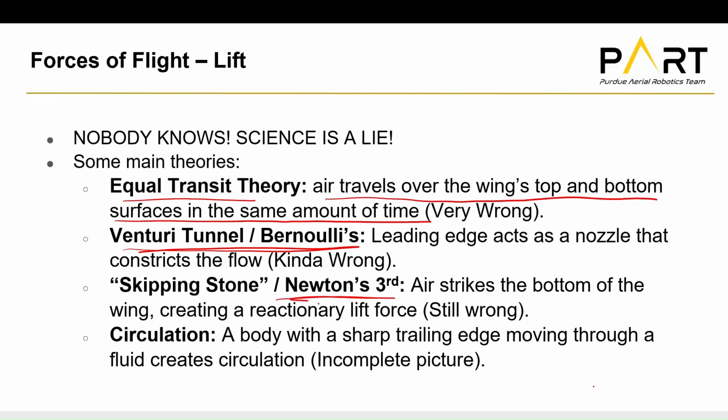Skipping stone or Newton's third, air strikes the bottom of the wing, creating a reactionary lift force. This is still wrong, right? This doesn't really account for stall. If you had a flat plate in the wind, this still stalls at about 15 degrees, right? And if you were just looking at air coming up and hitting it and bouncing off the bottom, then at 15 degrees, who's saying that this is stalling? This should keep on climbing to like 45 degrees, right?